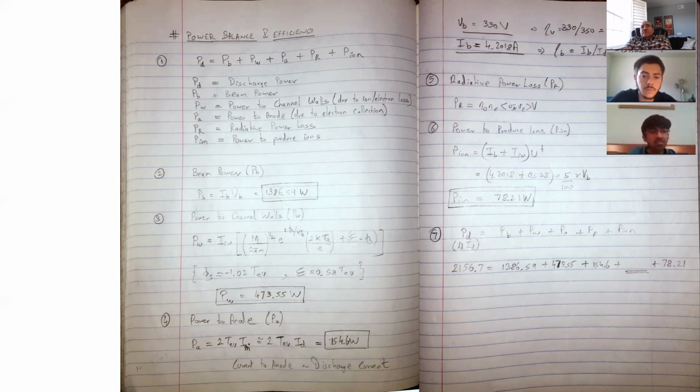So to ionize either from Xe to Xe+ or to Xe2+, let's say. Exactly, and then you multiply this by the mass flow rate and convert it to a current. The current times 12.1 electron volt times 4, which I don't know what the 4 is for, but that should be the power to make the neutral atoms become ionized. So you have to spend that. It's like a price we have to pay to create ions and electrons.